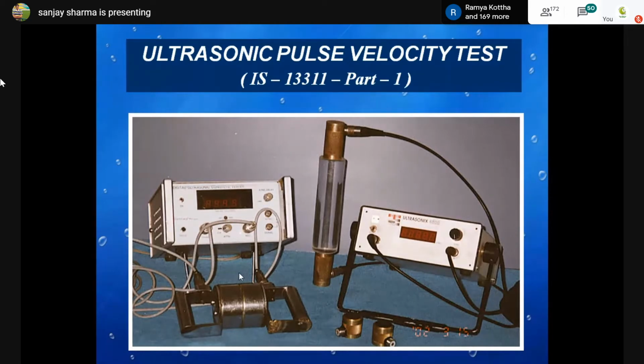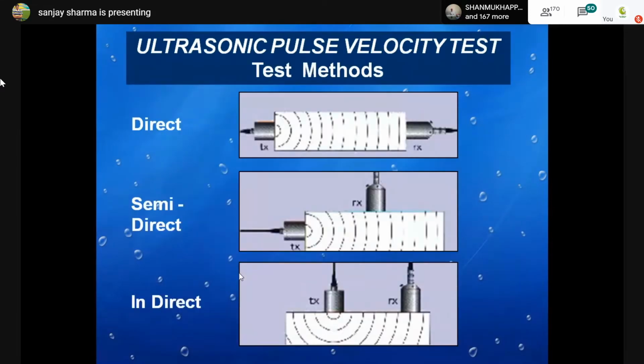By our calibration system, we know what the time taken means. It is a qualitative test, but it can be used as a quantitative test along with the hammer also. With the hammer, you have seen that only the strength of the cover layer is determined. In this test, we are determining what is inside the concrete. If the uniformity is the same, we can say that the concrete is of good quality.